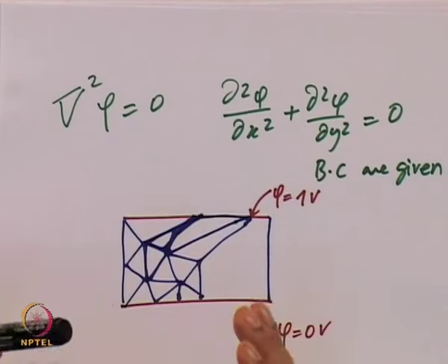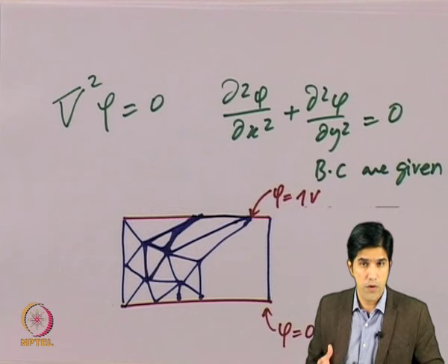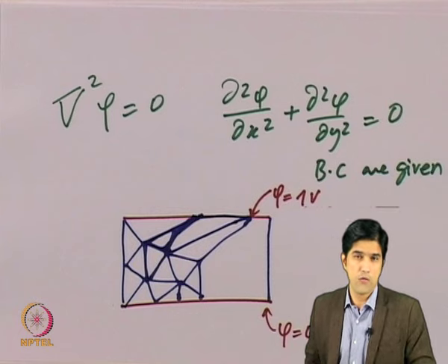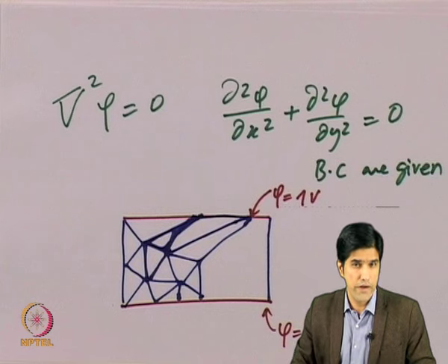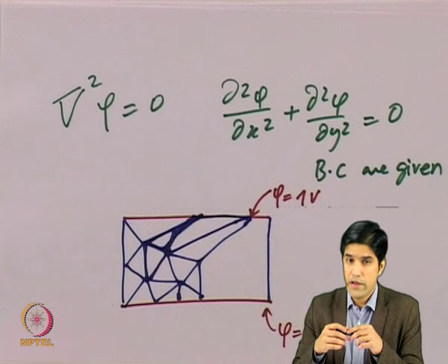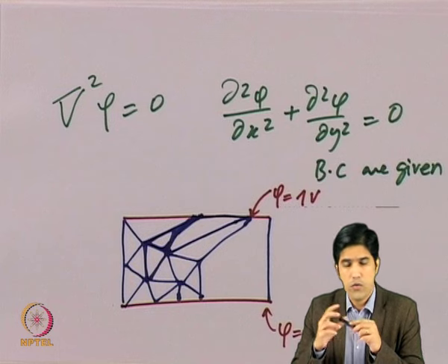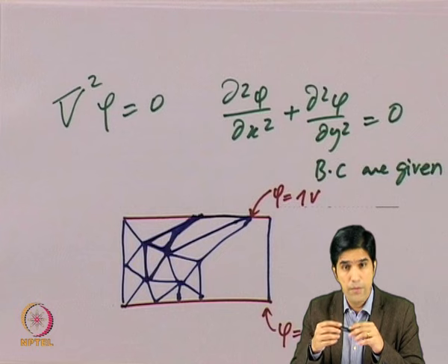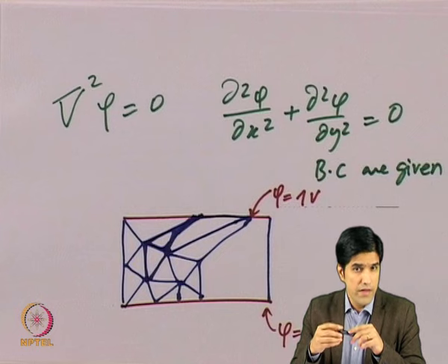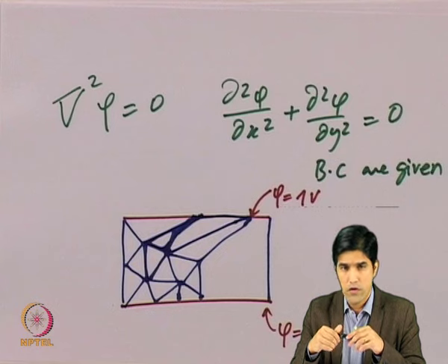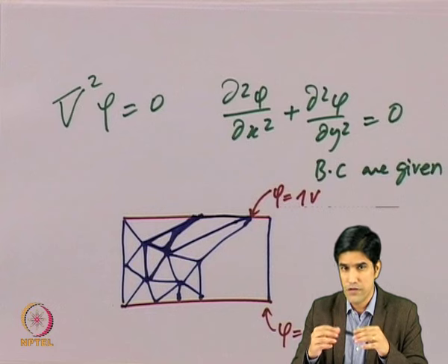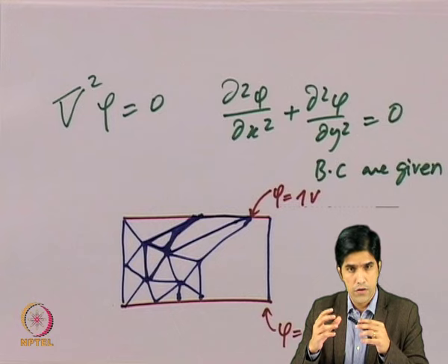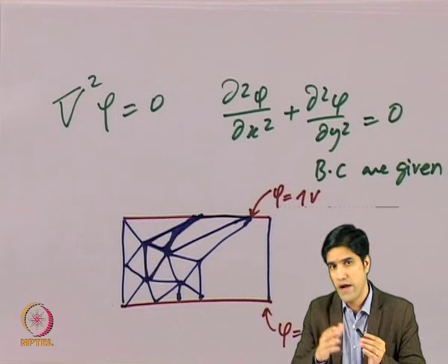If you have a mesh generator that is not very accurate, your problem should still be able to run on the outputs of those mesh generators. So we want a mesh generator that is very general. We cannot rely on the mesh generator's accuracy itself. What we can do is refine the grid, but we don't know the quality of the grid that will be produced by any mesh generator. That being said, the program you are going to use for solving such a problem should be able to solve the problem using any mesh. Of course, we need to look into the numerical accuracy that we need. If we need better accuracy, we have to refine the grid.